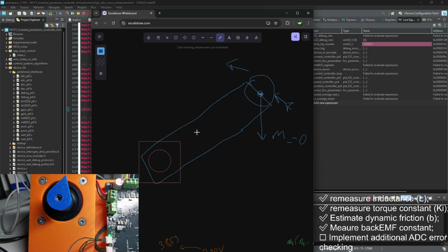But yes, so we will add here like 200 grams, maybe 300 grams, because we know the torque constant here. So we know our limits, and depending on the length of this crank, we cannot load much more. And we will make sure that with software, we actually feel 0 weight on this thing. Not 0 because we don't have an exact model of the motor, but it will be very close to 0. So this is one of the examples we will implement soon.